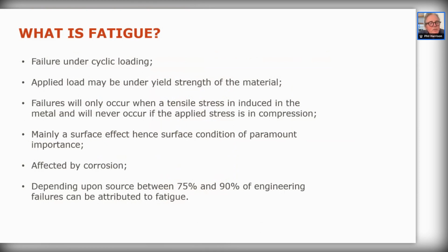So that is straightforward rotating bending. So what do we have that cycles, that goes up and down? We have car springs, for example. Let's just look at automotive. Car springs, gears in cars. So anything that's moving can undergo some form of cyclic loading.